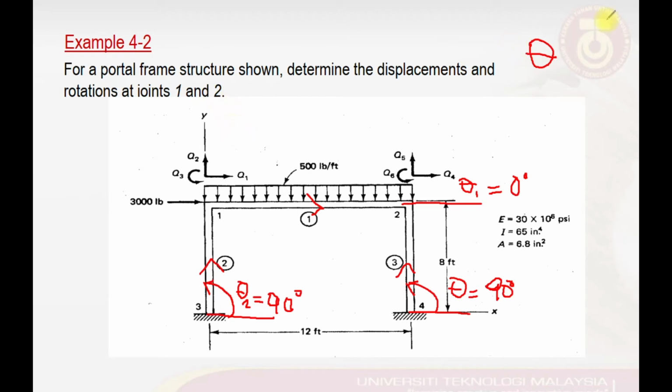But what will happen if, for example, the connection for element number 2 is instead not from 3 to 1, but let's say this element is now connected from 1 to 3? In this case, our starting point is here, where element number 2 is connected from 1 to node 3, so we start here. I will draw a horizontal line at node number 1 and start measuring the angle.